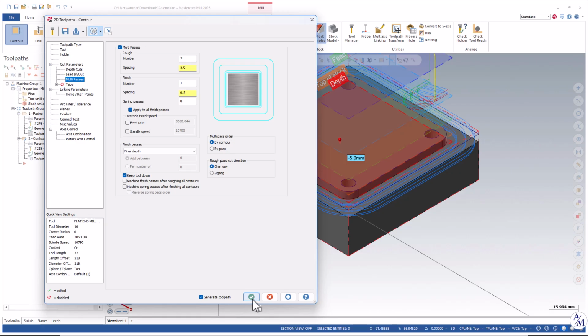Okay, so normally when we are setting up the tool path, we need to avoid unnecessary paths. For example, we can make sure that by giving 5 passes, it will remove the entire material. These 2 passes are really not necessary. So this is waste of time. In industry, waste of time is waste of money. So we should not do that. So that is, we need to make an optimum tool path. So let's keep it 3. 3 is essential. Good. Click OK.